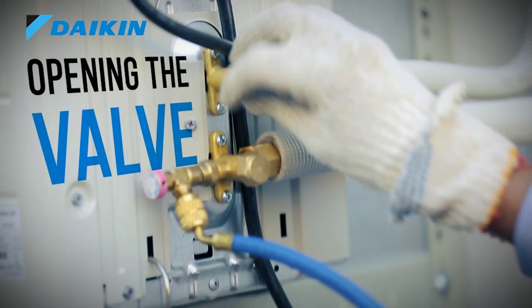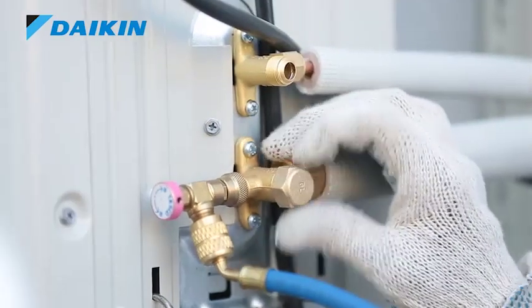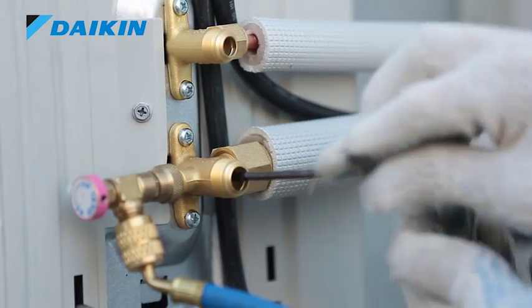Opening the valve. Open the liquid line and suction line valve using the correct size of Allen keys.